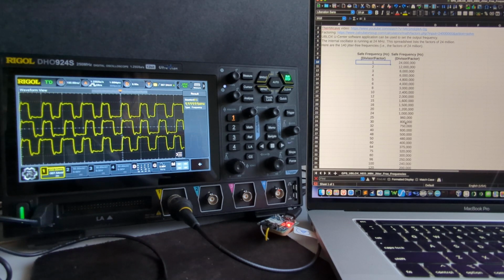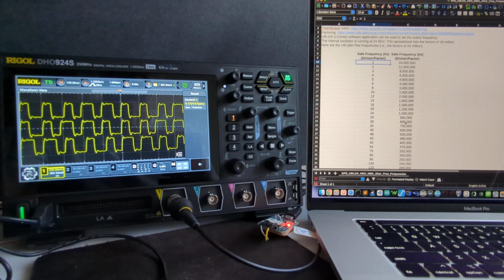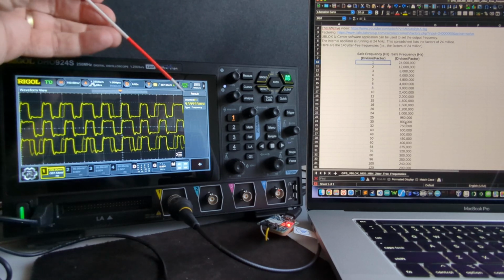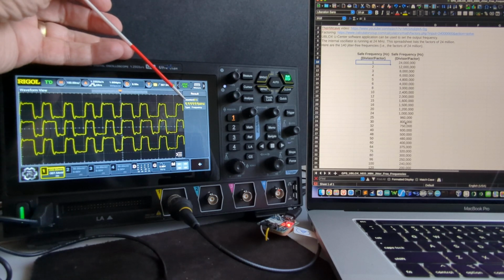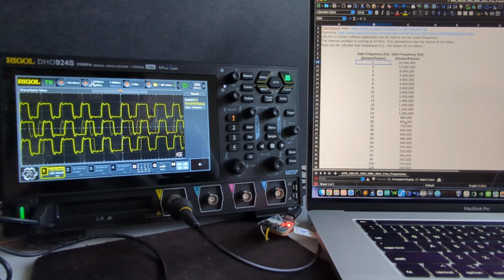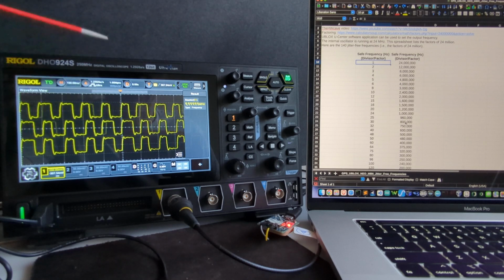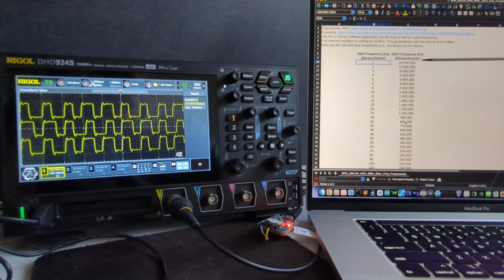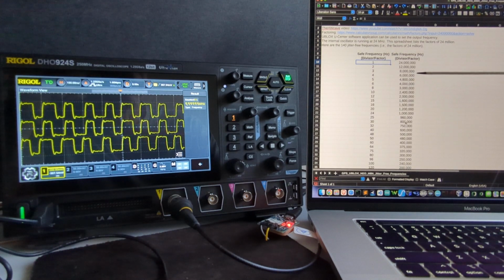So there's 10. And what is happening within the UBLOX GPS unit is they have software in there that's working to deliver the desired frequency. And here you can see it's 9.99999 megahertz, basically 10 megahertz. And in order to achieve that number of cycles per second, if you will, 10 million cycles per second, they have to vary the mixture of 12 megahertz and 8 megahertz waveforms.